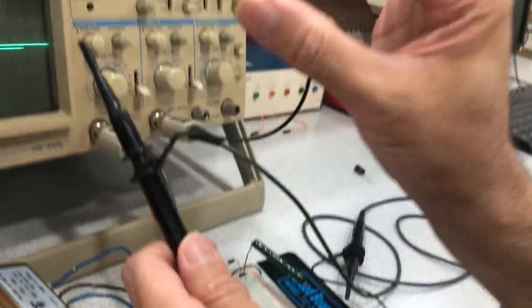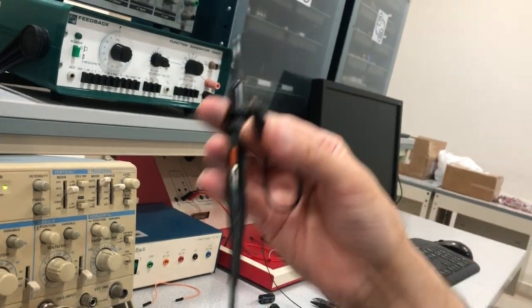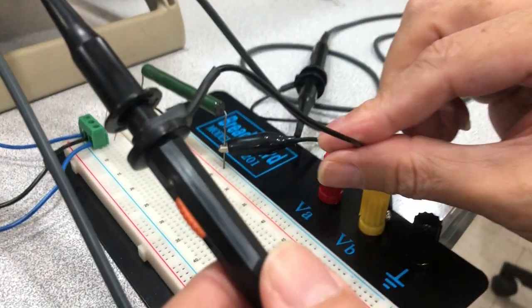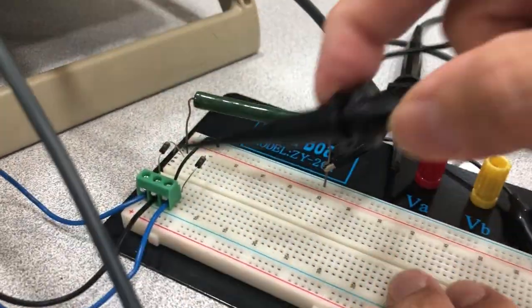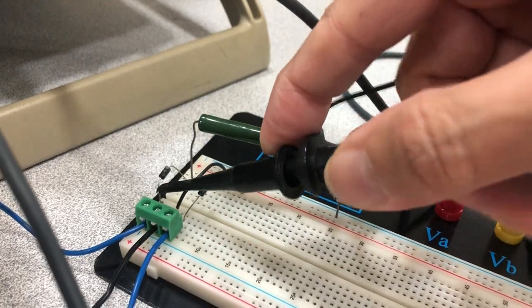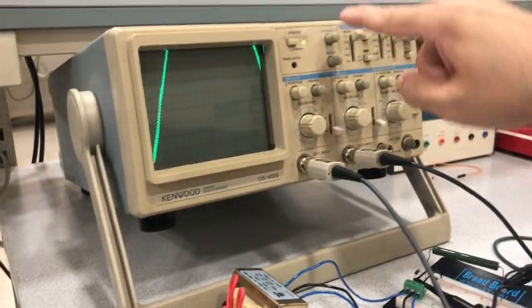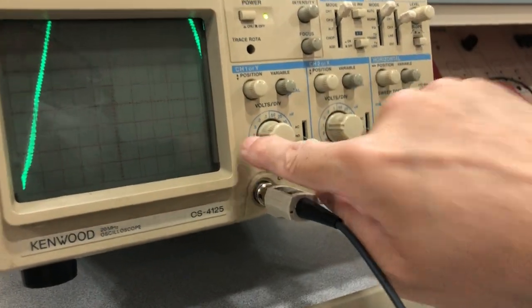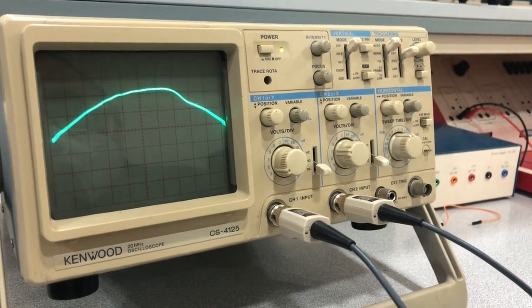Basically, the ground is connected to the shield so that this scope will measure only the signal of interest under test. So we put this shield wire on the ground of our circuit, and we put the tip hook on the sinusoid. So now if I plot channel 1, I have a sinusoid, and I can see I'm exceeding my volt per division. So I have to go to, as we said before, 5 volt per division.